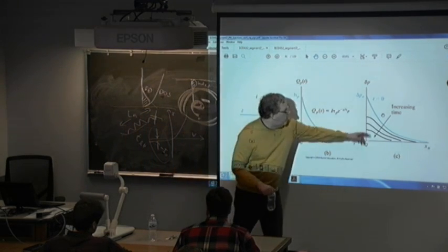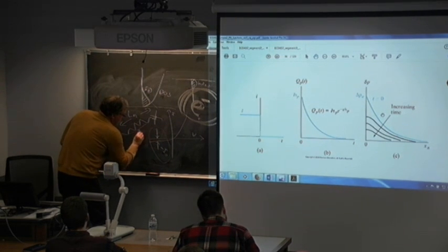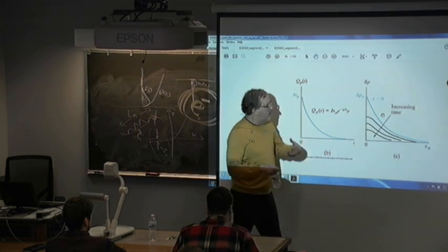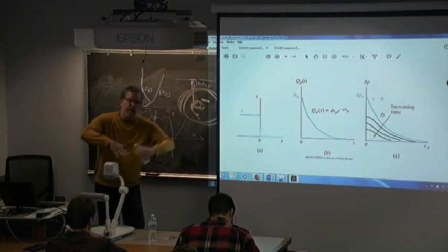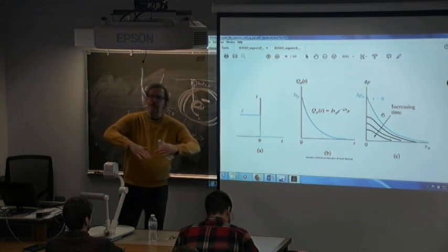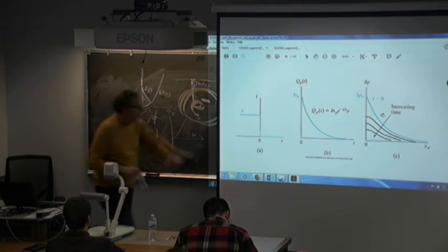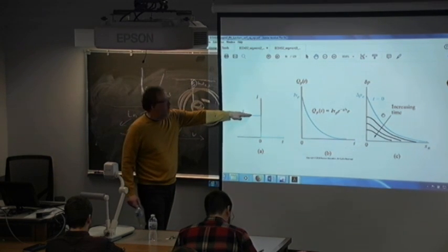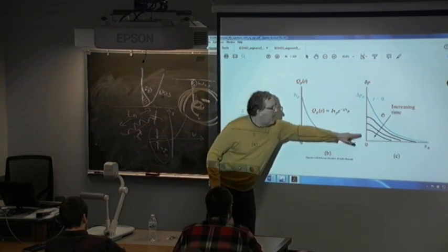So one time constant, let's call this tau to be consistent. One time constant, two time constants, and eventually it should all disappear. So it'll reestablish and move back to equilibrium. Remember, Mother Nature always wants to come back to the np naughts and the pn naughts. It wants to reestablish equilibrium whenever there's a perturbation, and this is a perturbation, right? I've disturbed equilibrium by forcing current through it. And then I go to 0, which is equilibrium. So everything quiets down and everything relaxes back, right?